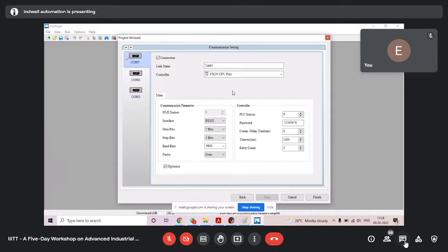Okay, clear. There was one question: how does a motor rotate forward and reverse? Ravi Teja, we will see forward reverse while we make the program. Understood. Okay. Next, you see, you have to do finish. So these two things you have to do. Select your HMI hardware, then select your PLC and COM port number of HMI. Done.